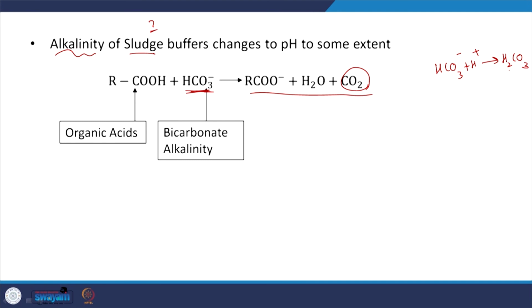I guess with that I will end today's session. One aspect to note is that with an anaerobic digester, you have to cater to the needs of the system, primarily with respect to pH, hydrogen buildup, and the methanogens, which are very sensitive to temperature. These are the aspects that have to be taken care of. In the next couple of sessions we will look at the different kinds of stabilization, and then more or less finish this particular course. Thank you.